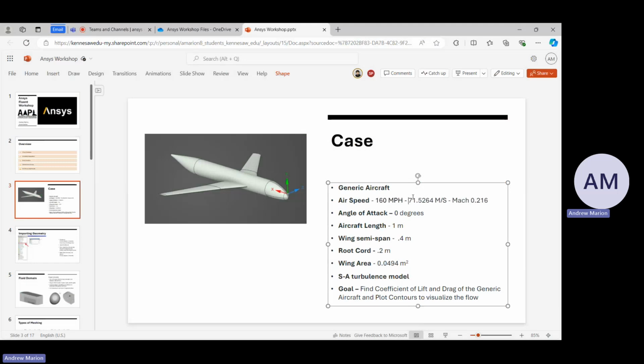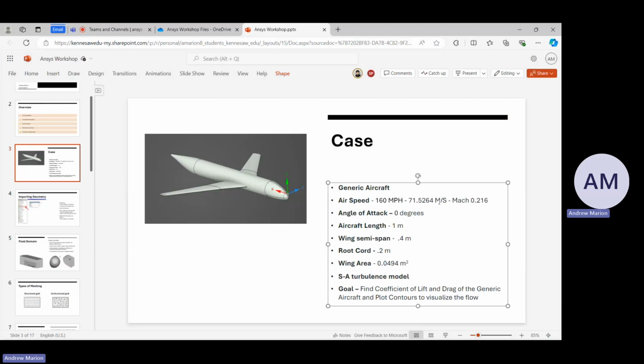A little fun fact about the World War II Spitfire: it had a perfectly elliptical wing, which gave it nearly mathematically perfect lift over the entire wing. The problem is, due to being mathematically perfect, it had no twist in it. So when the wing stalled, the entire wing stalled at the exact same time.